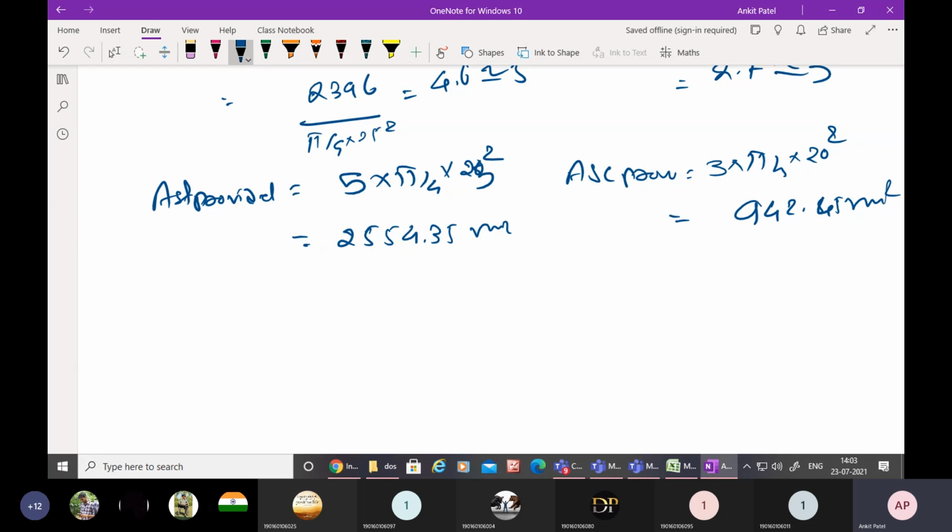But please remember this thing, this is really very important and very necessary. What is important is, after designing we must cross verify whether our section is under reinforced or over reinforced. So for that again please remember, this is not given in any book.